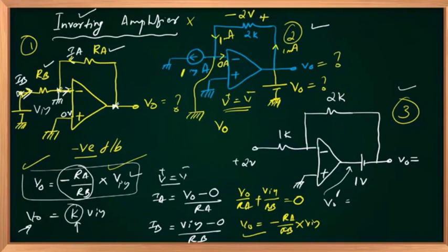Then plus to minus, 2 volts, so I should take it as negative 2, because negative to positive I took as plus. So minus 2. I have started from ground, I have taken this, and I have reached here. This is actually a ground. So it's a closed loop. So that implies V out equal to 2 volts. And this formula is not going to work.